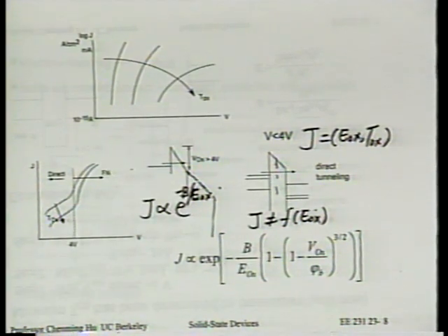Roughly speaking, in this range of 15 angstrom or so of the oxide thickness, every 1.5 angstrom change will raise the current density by a factor of 10. Okay, you reduce by 1.5 angstrom in thickness, you get 10 times more current.